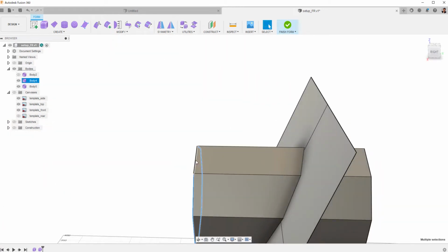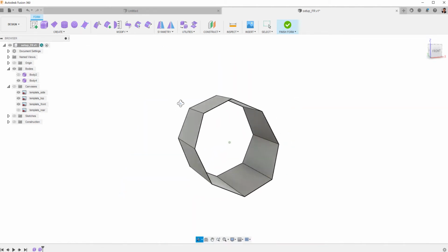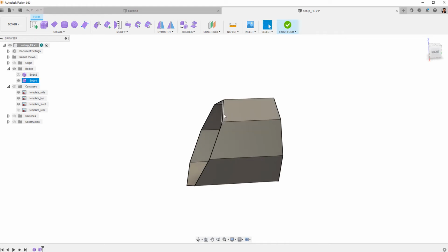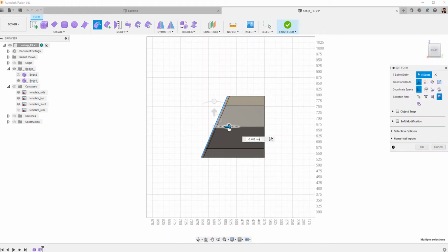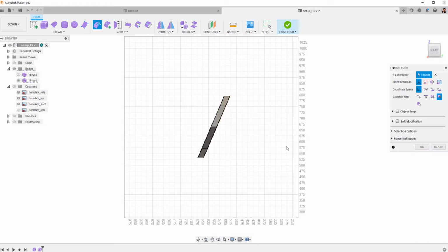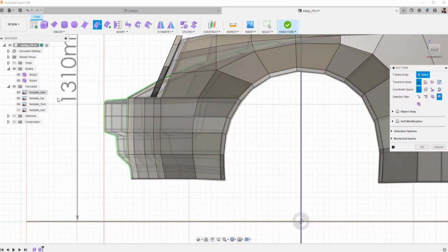When an intersection is made, delete the unnecessary front side. Delete this plane as well. Double-click an edge and press Alt to extrude. Delete the backside so that only the extruded faces are there. Go to side view and move the cylinder to fit the template.